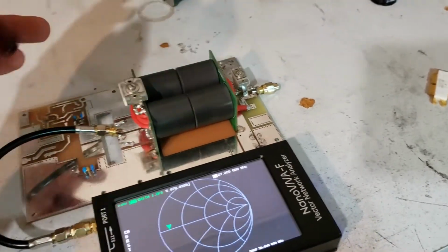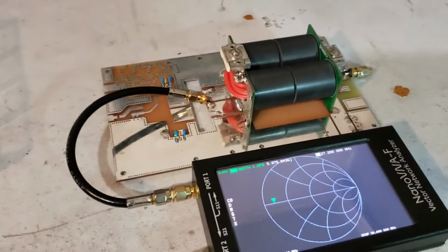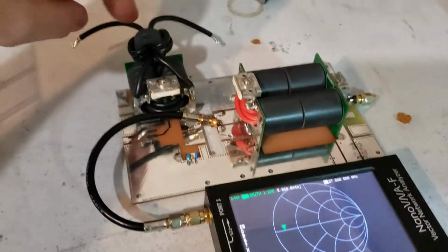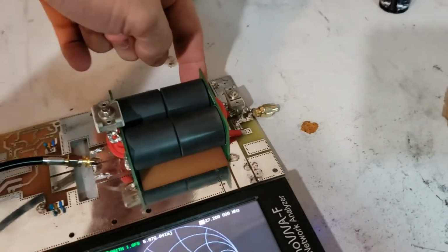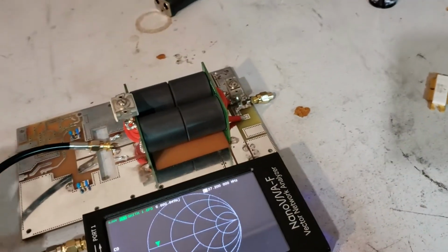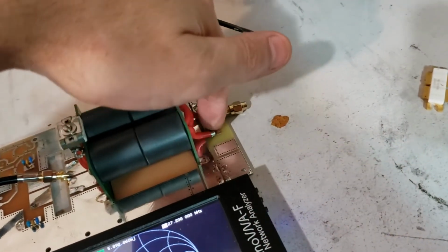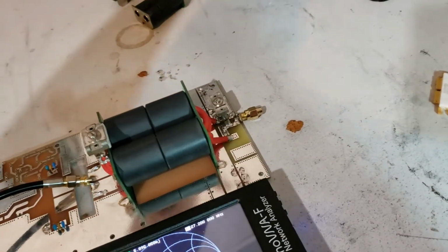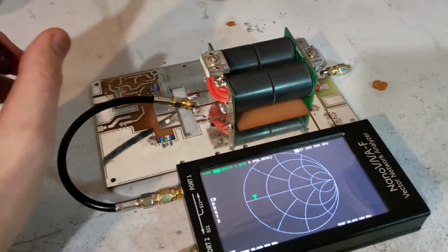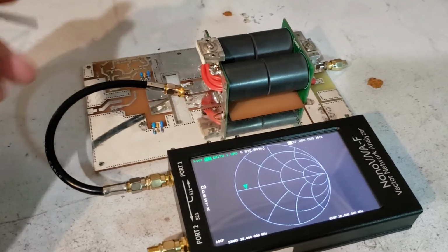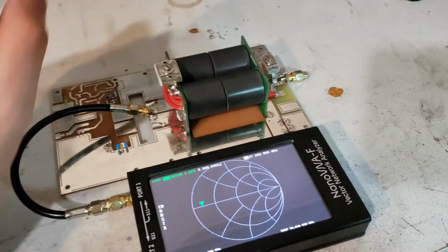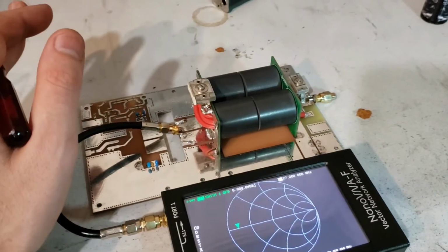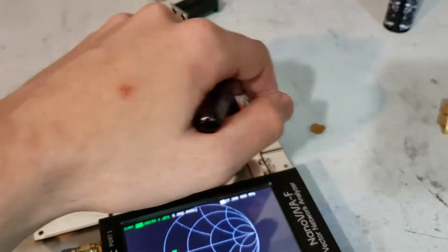So right now this is just a transformer on a board. As soon as you start hooking up other things, like your choke, if you hook this choke up, your impedance is going to change. You put a capacitor on the other end of the choke, your impedance is going to change a little bit. You connect a piece of wire to this and feed it into a relay, your impedance is going to change a little bit. So if you actually are going to do this measurement, make sure everything on that side of the transformer is 100% installed, including your tuning capacitors.